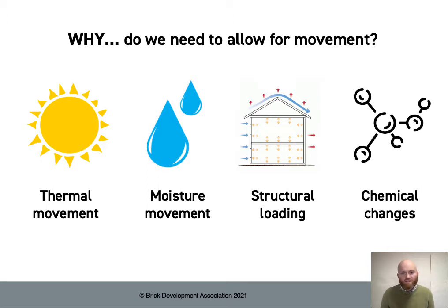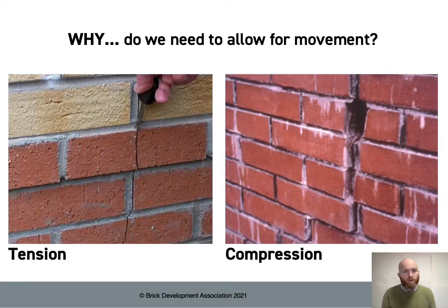Clay brickwork, like I say, is generally subject to long-term expansion, whereas concrete masonry, which is concrete blocks and aircrete blocks, does the opposite. They tend to shrink over their lifetime. So if we don't allow for that movement within the brickwork, we can end up with a scenario like this. The movement can mean that there is a build-up of internal stresses within the brick and the mortar, and that can lead to cracking, whether through build-up of tensile forces, as you can see in the image on the left, or due to compression, as you can see in the image on the right.